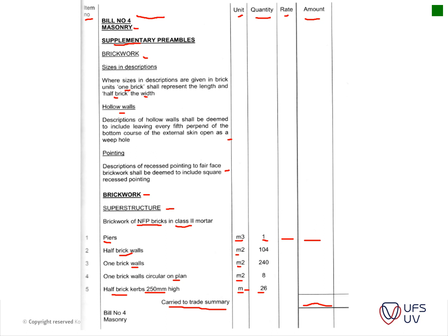Obviously there's still a lot of items that are not listed here. For instance, your reinforcing is not measured here. If there's face brickwork, it's measured separately, as is brickwork in foundations, and a coating that has to be put on to the brickwork. Then your bills will usually go over a couple of pages.